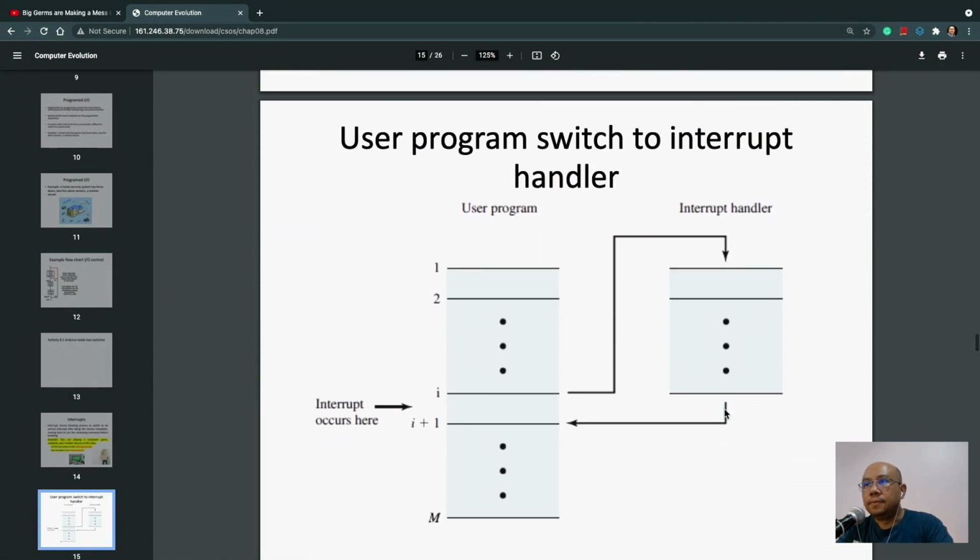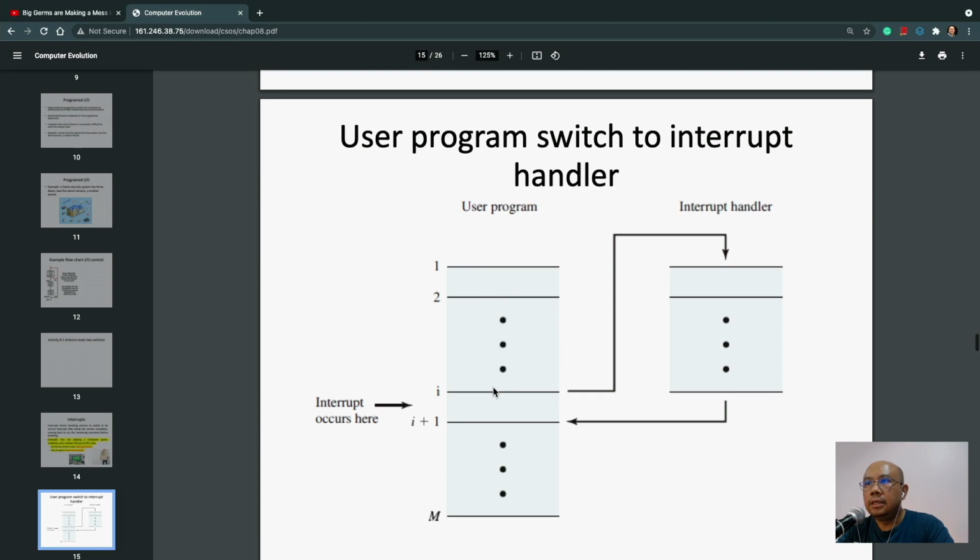Here in this picture, the program running here is the main program. During the run, there is an interrupt signal from the external device sent to the CPU. The CPU switches from this work to service the interrupt. After that, when the interrupt is complete, it moves back to the main program to run the remaining code. Yeah, this is the interrupt.